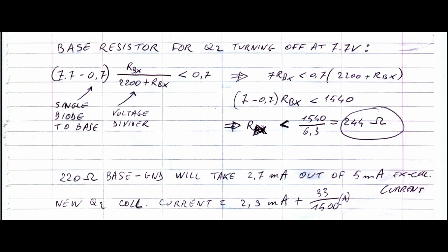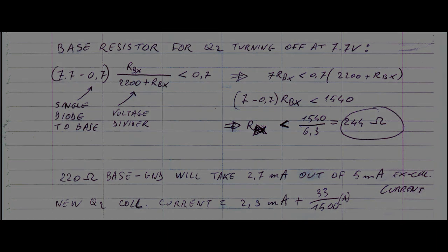This isn't a good idea in my opinion, because it would change Q2's operating point quite enough, and this may not be a problem, but the other issue with this fix is that it would probably never work, as it would depend too much on the actual gain of both Q1 and Q2. They would be racing one against the other, and probably there would still be a voltage window to have Q2 conduct enough current to make the spot appear. If someone wants to try this route, however, can let me know how it goes in the comment section below.